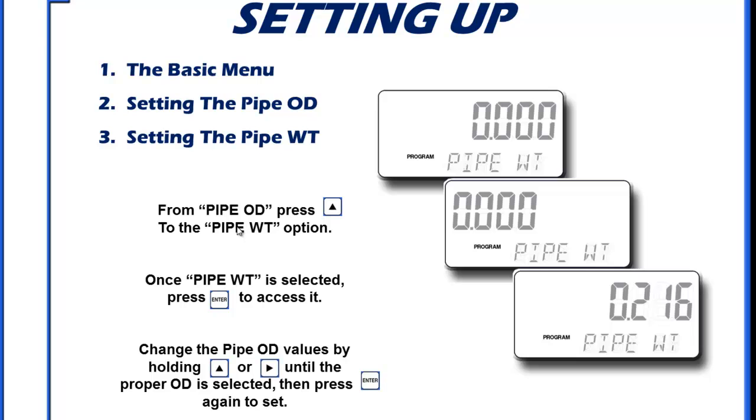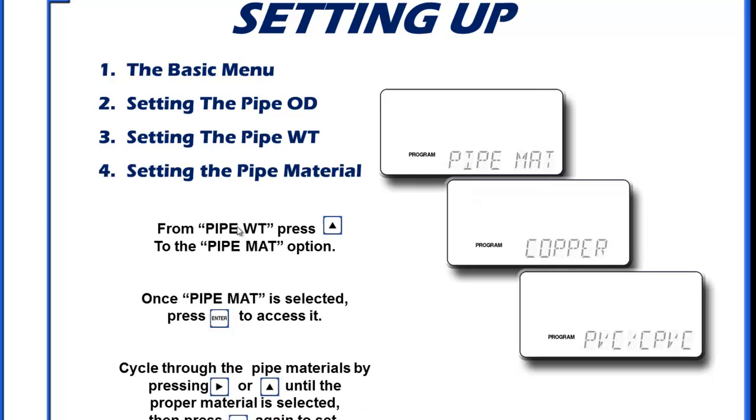Now, if you have an ANSI pipe, everyone asks, is it schedule 40, schedule 80? Based upon doing this a zillion times, almost always you have a schedule 40. There'll be some exceptions, but they're relatively rare. When you have a very small pipe application, the numbers are insignificantly different, in tenths of an inch. With a very large pipe, it can make a substantial difference in your flow calculation. So start off with schedule 40 to get your pipe information.